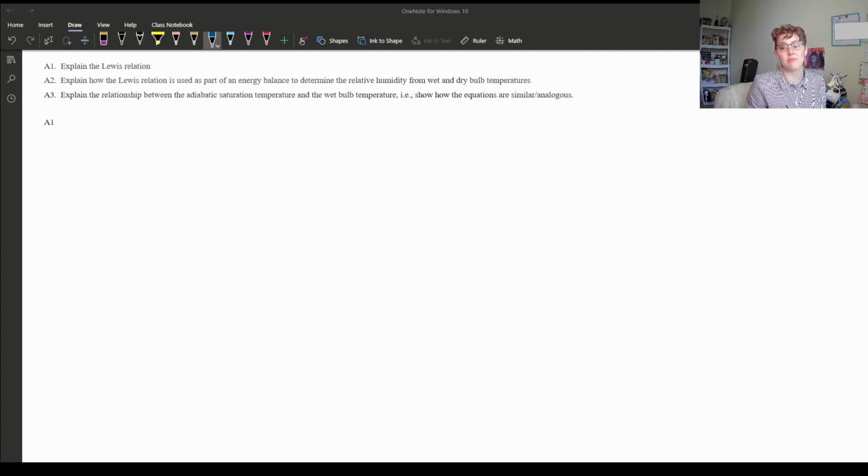Today we are going to be completing the third portion A, and the next video will cover portion B. As you can see, the goals for today are going to be explaining the Lewis relation and then how it's used as a part of the energy balance to determine the relative humidity from wet and dry bulb temperatures, and then explain the relationship between the adiabatic saturation temperature and the wet bulb temperature.